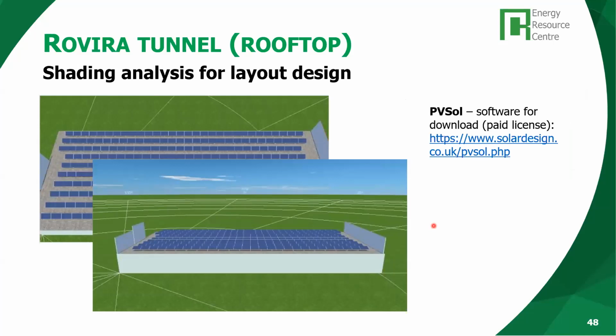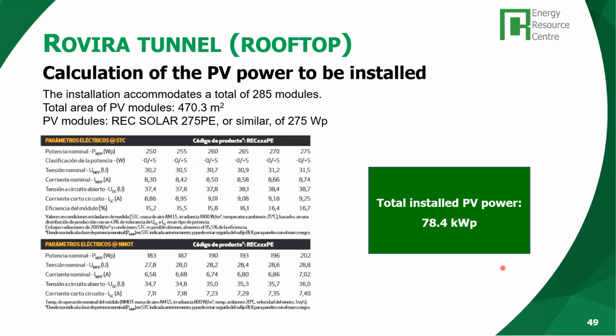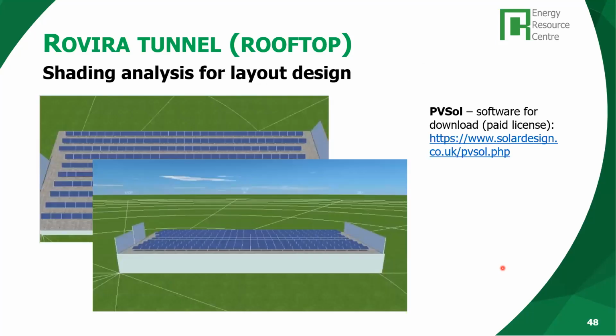Yes. You mentioned now the use of PVSol, huh? Yes, PVSol is very good because it works very well with 3 dimensions. You can draw all the modules in 3 dimensions, and we have a specific tool to calculate the shadows and to get the losses that you are having from the shadows.